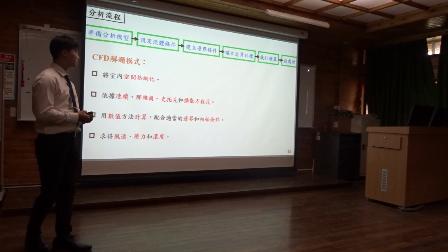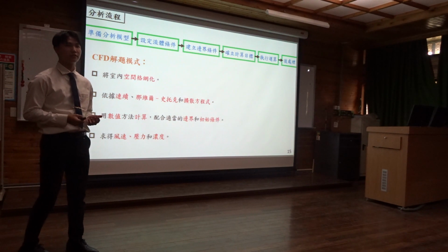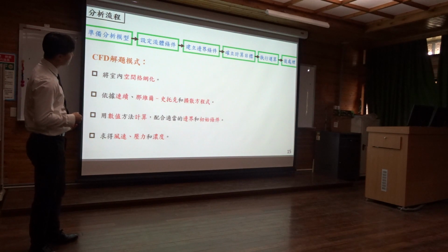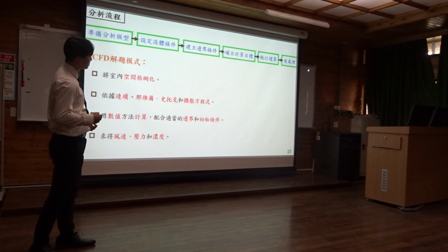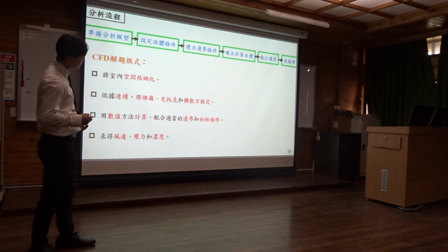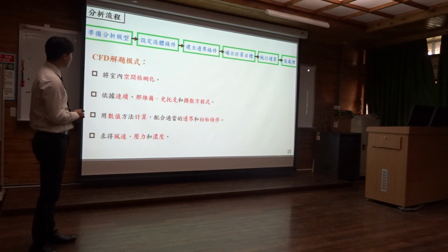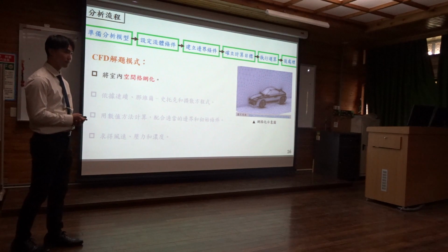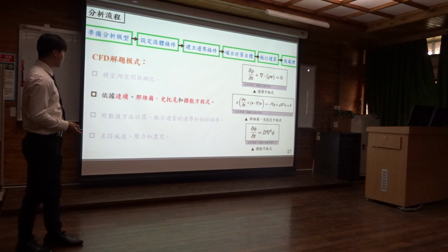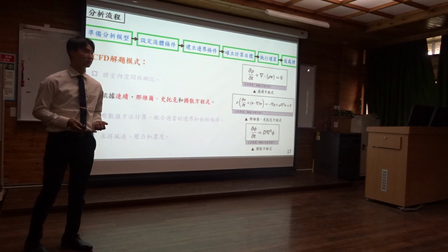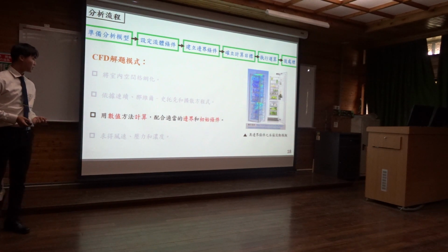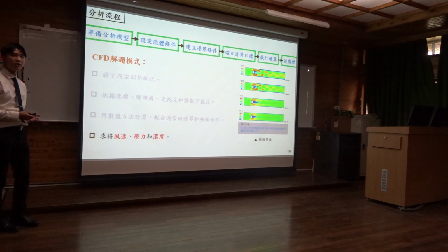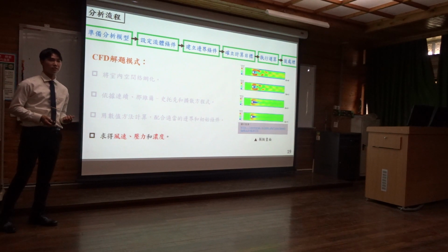Here, we can see the analysis process of the entire simulation: preparing the model, setting the fluid condition, building the boundary condition, establishing computing goals, running the calculation, and post-processing. The CFD simulation process involves indoor space gridding based on the continuity, Navier-Stokes, and diffusion equations. Using a numerical method with appropriate boundary and initial conditions, we calculate the velocity, pressure, and concentration from the simulation.